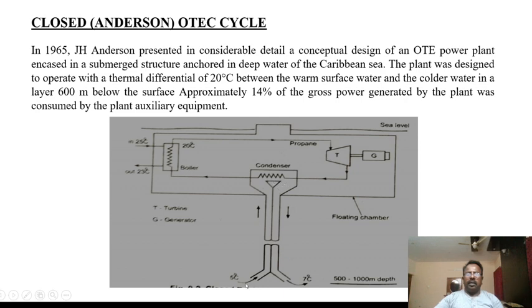The cold water entering the condenser gains heat from the working fluid, and the water with a temperature rise of nearly 2 degrees centigrade is released again to the sea beneath. So this is one portion and this is another portion, and this is internally connected with the float.